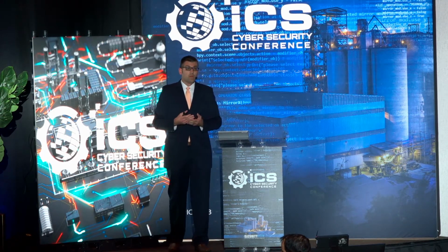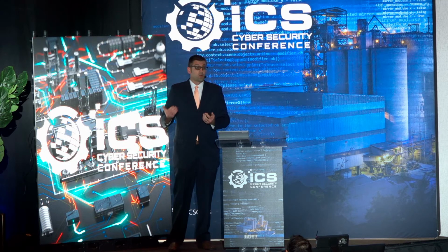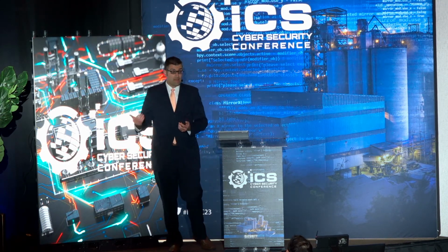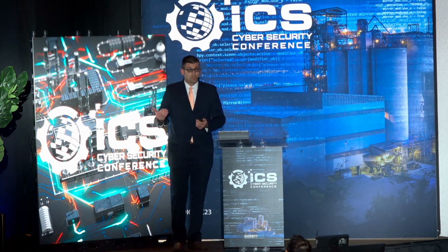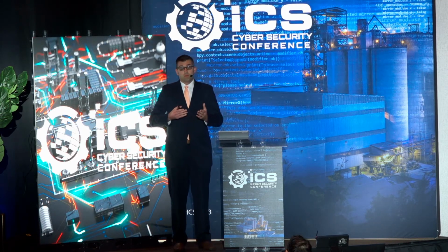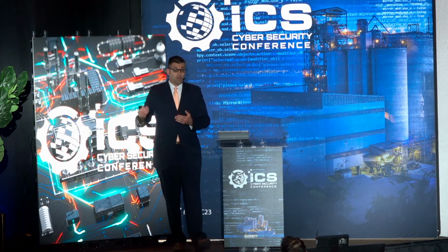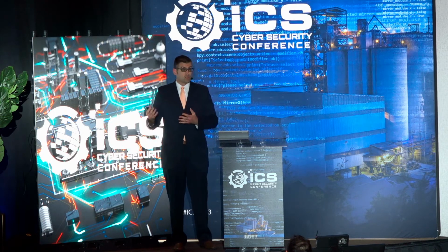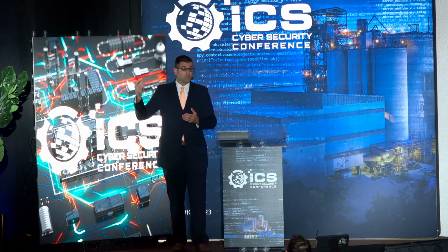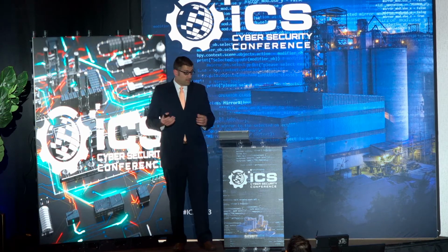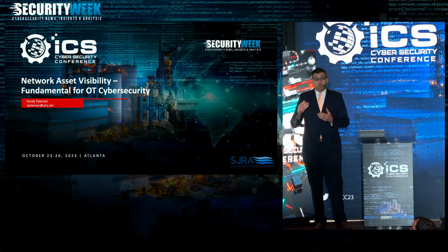I came out there and we were looking at a lot of manual systems and manual operations. Operators were going out, turning things on and off by hand, spending windshield time driving between all these different sites to check levels and check pressures. Then we wanted to move into automation. So we started putting out the instrumentation, PLCs, all the wiring, network switches, and servers to run our HMIs, historians, and interfaces into business networks. All of that brought up the big, scary thing that we needed to address, and that was cybersecurity.